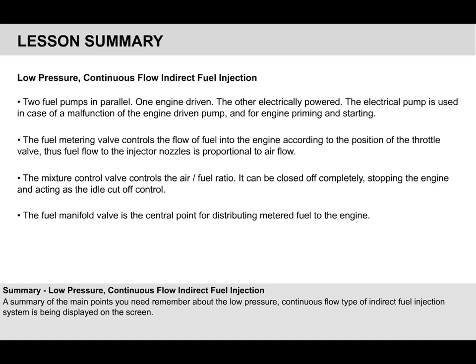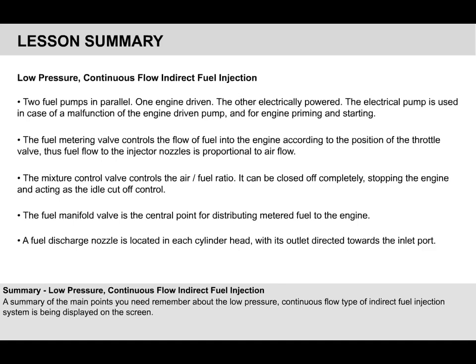The fuel manifold valve is the central point for distributing metered fuel to the engine. A fuel discharge nozzle is located in each cylinder head with its outlet directed towards the inlet port. When you are happy with all these points, move on to review diesel engine fuel injection.